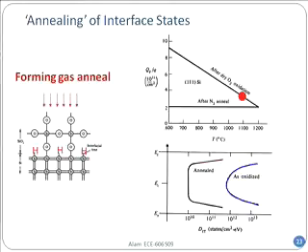And you can see here that number is on the order of 10 to the power 12 if you do not do any forming gas anneal or do not tie it up with hydrogen. But as soon as you do so, the number reduces to 10 to the power 10. And this today is what you need for a good operating MOSFET that you can buy for your Pentium and other processors: numbers on the order of 10 to the power 10 states per centimeter squared.